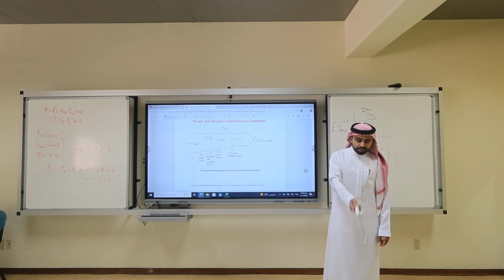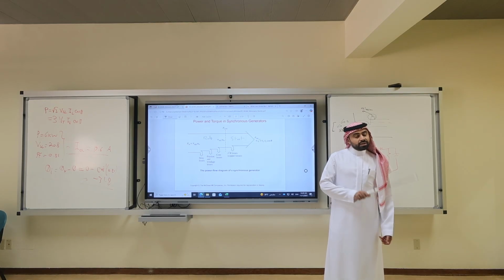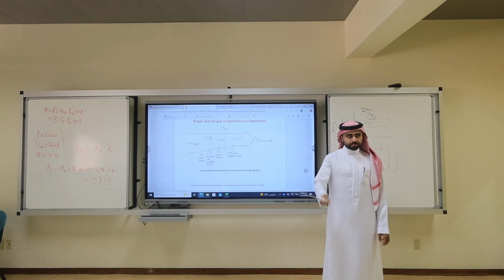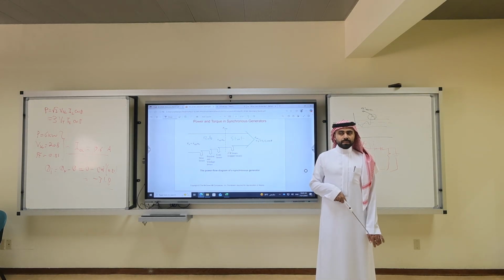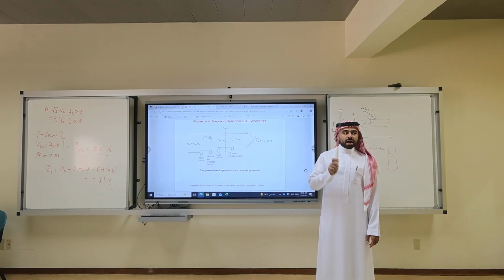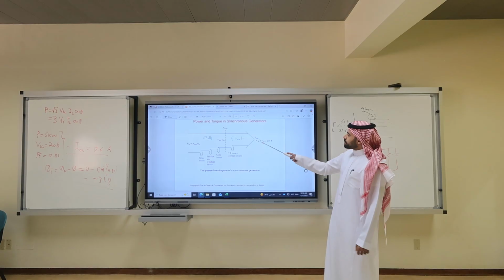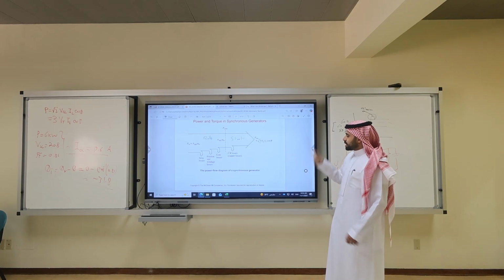Do we consider R rotor? But for the induction motor, we had to include both the stator and rotor. You remember that? We have XS, RS, RR, slip. Then the output power is square root of 3 VL IL cosine theta.